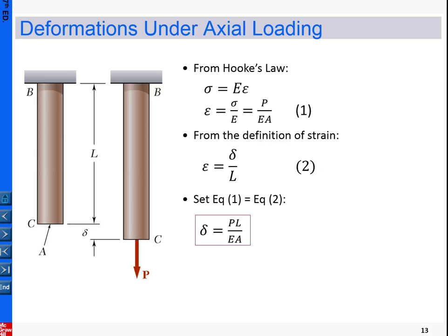So here we are assuming the cross-sectional area of this is A, assuming that it is uniform throughout the whole bar. So from here we will be able to calculate stress equal to the magnitude of the force P divided by area. And we also measure the deformation, which is the difference between the deformed model and the undeformed. So delta we can measure here. Strain is calculated by dividing deformation by the original undeformed length L.